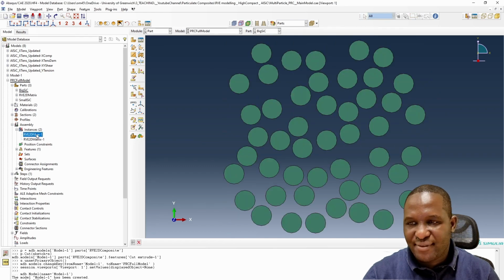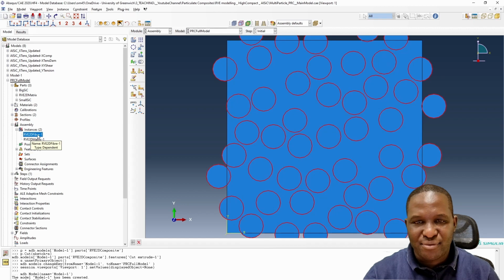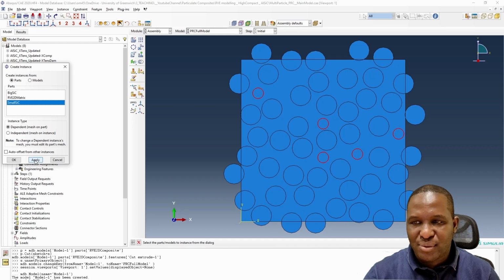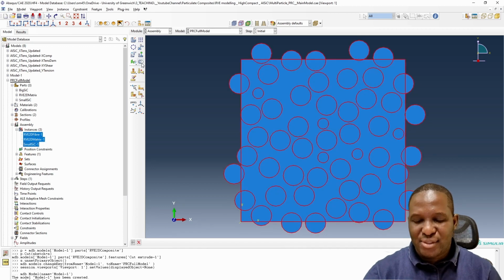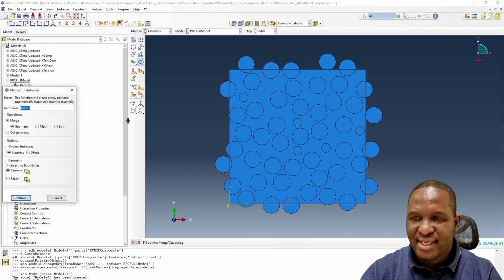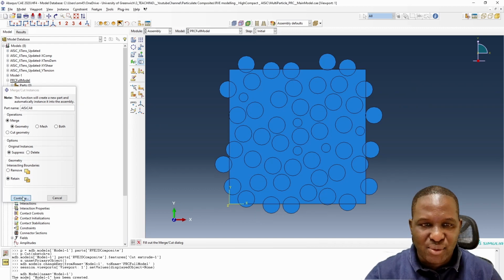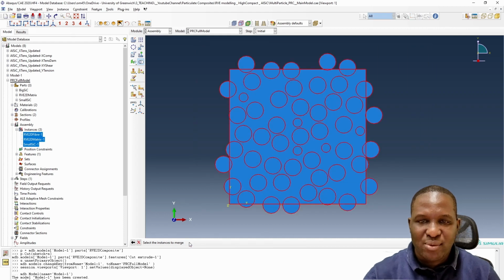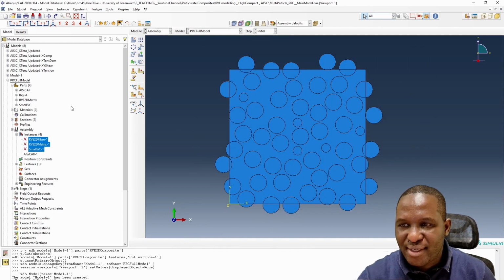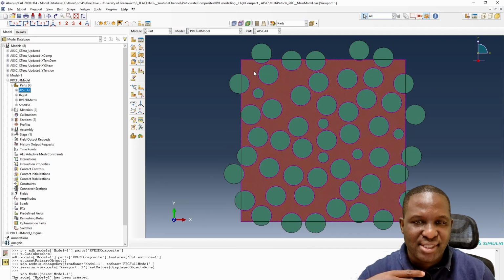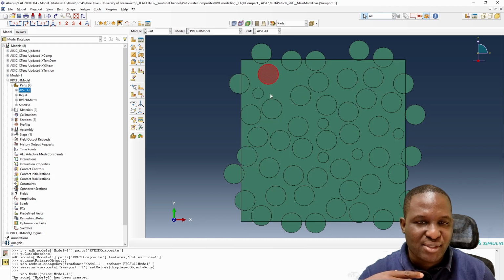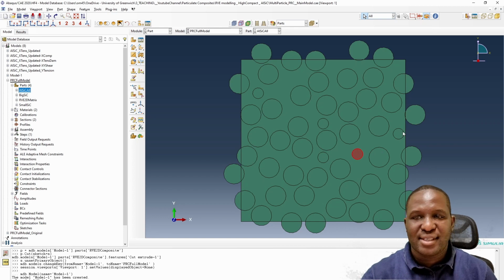Okay, so we have fibers, which is the big fiber. We've got the matrix. So the only thing we didn't have is a small fiber, which we have now. So we've got all three in their window: small fiber, big fiber, and matrix. If we combine all that and click on this, we can now say, okay, aluminum silicon carbide, return, and you select all those continuously. So what you now have is a complete model. If you go back to your part, you can actually see aluminum silicon carbide, which consists of the matrix, the big fibers, and also the few small fibers that we have set.